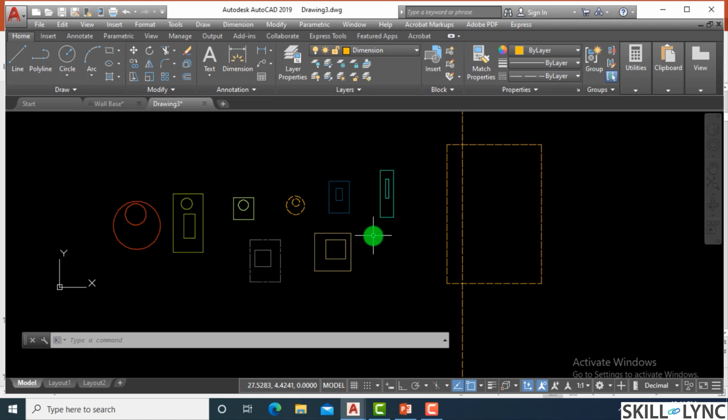You can give a color by the ACI, the AutoCAD Color Index. You can give the color by true colors or the AutoCAD color book. So you can assign colors by RGB, HSL, any other thing. AutoCAD has a library, which is the ACI, which can be used for defining the color. Normally the CAD standard uses the ACI, that means the index color. You identify a color by a number, like 19, 20, 38, right?